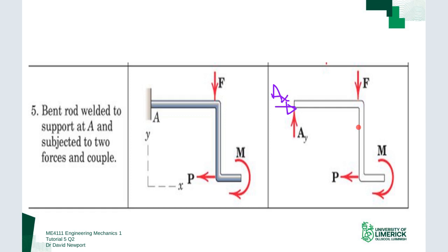And because this is a built-in support, now if I have this cut and I try to rotate either way against this, about this point, it would react to it. It would try and stop it. So I would expect a moment reaction.